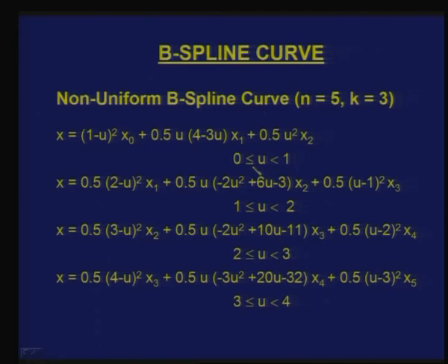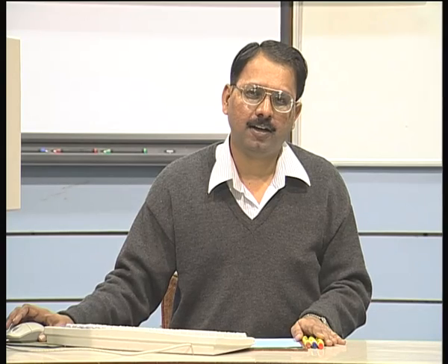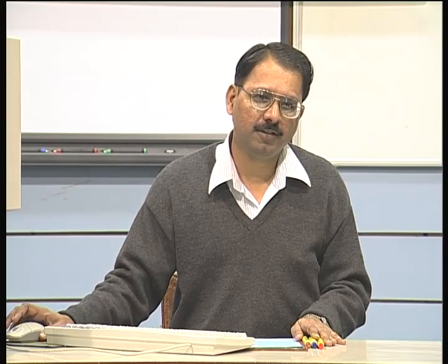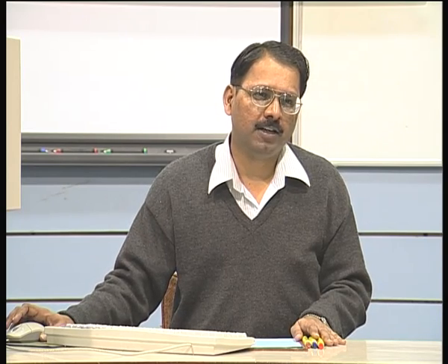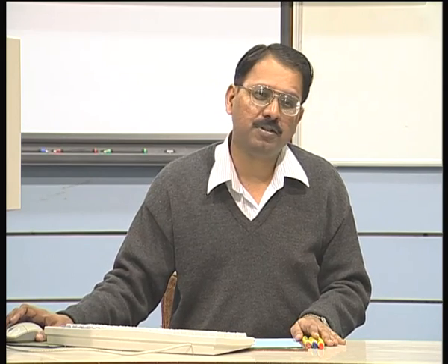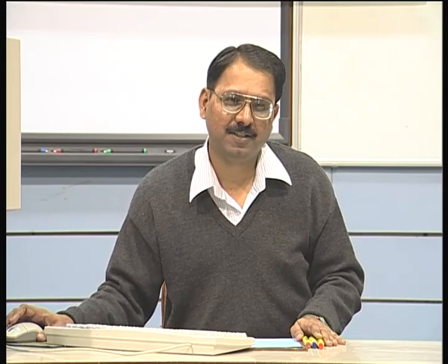Now, if I choose, for example, k equal to 4, then I will have a different equation which will have terms x0, x1, x2 as well as x3, and all these values will change. So, I have different functions which will define the curve when k is equal to 4. And if I want to display or plot the curve, or take a cutting tool along this particular curve, and evaluate a number of points on the curve, then you need to use different equations for the different segments of the curve.